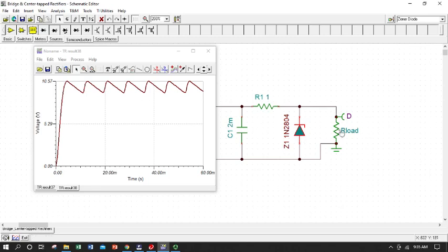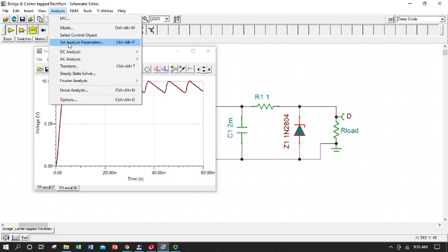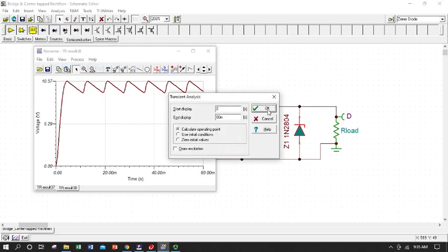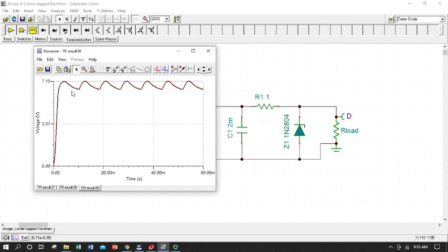So we've got a 100 ohm load, and we have our 6.8 Zener voltage regulator plugged in, so let's run another analysis and see how that changes things. We're going to assume that our external circuit is okay with just 6.8 volts, knowing that we could always adjust that. So we're going to run it again, and we've seen the waveforms changed a little, and most important, our y-axis value changed to 7.15.